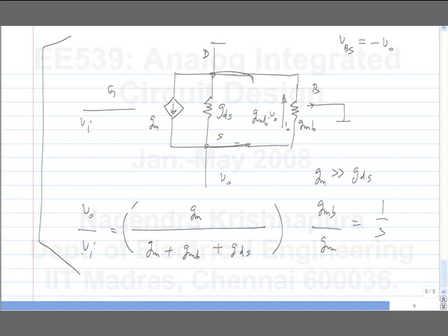Also here you can see that GMB is not a good thing, right? For the common gate amplifier, we saw that it made it better. It made the input impedance better and it made the output impedance better. Whereas for a common drain amplifier, it makes it worse. Okay, it makes the gain worse. Is it okay?